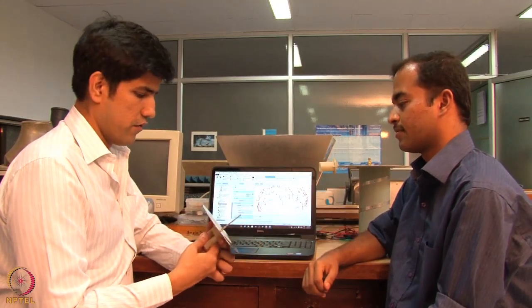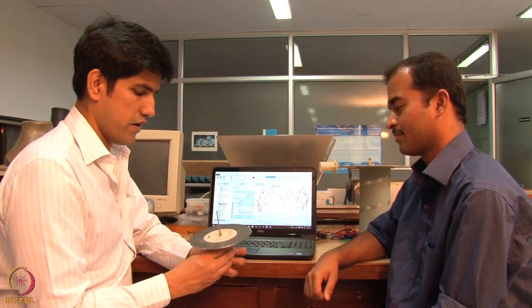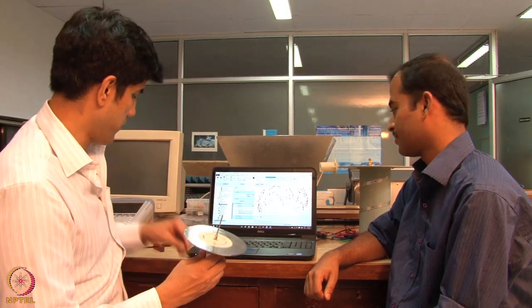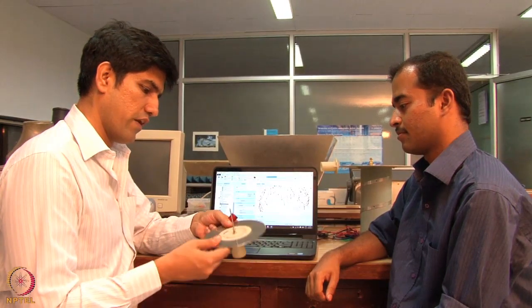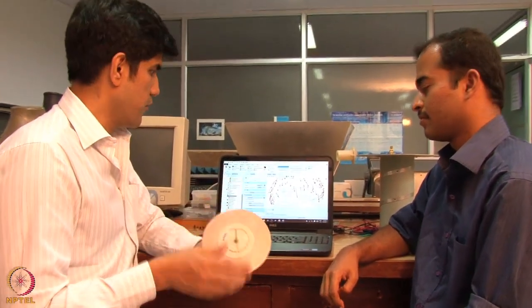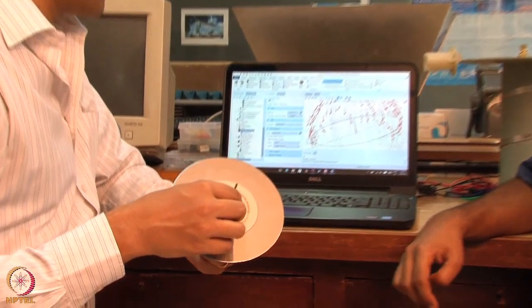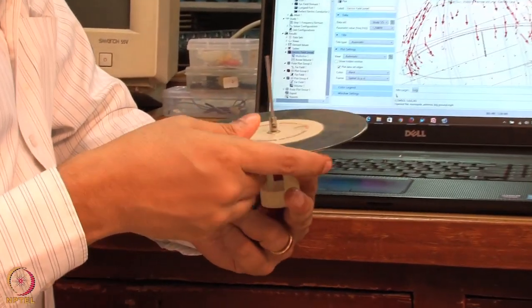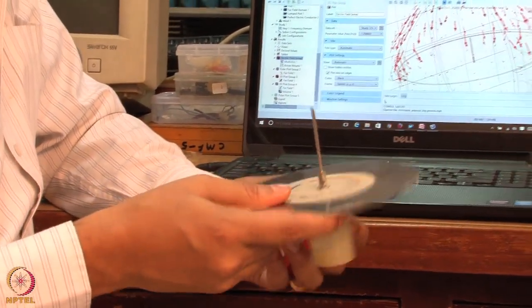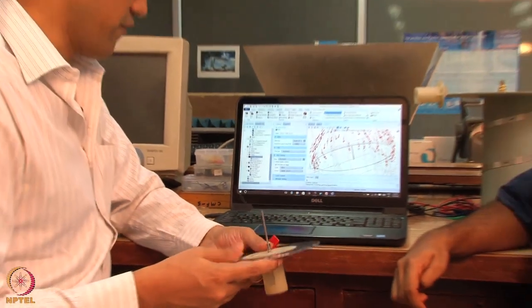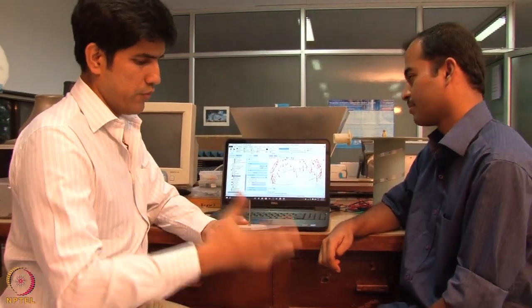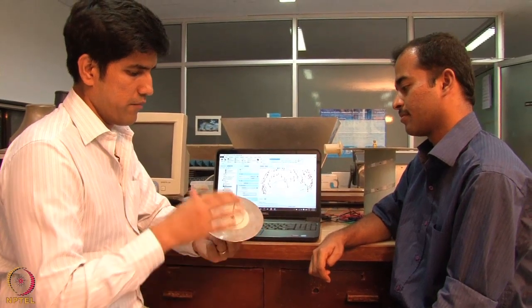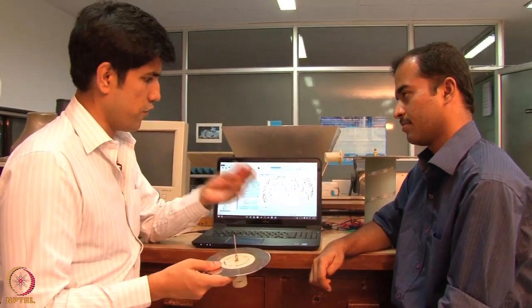Okay, excellent. Thanks a lot, Aviraj, for showing us two problems. One is using a permanent magnet, and the other is using a monopole antenna. For both of them we have looked at a finite element solver, where we can model such practical problems and get practical results, so that we can improve the design of certain antennas and the directivity of the antennas. We're also looking at magnets, their strengths, and the pole strength and things of that sort. So thanks a lot. Thank you.